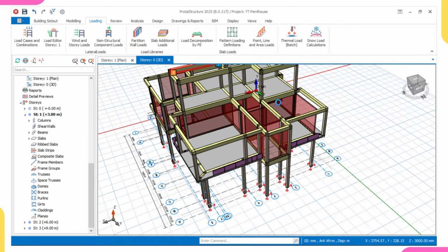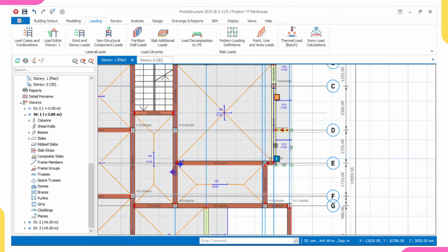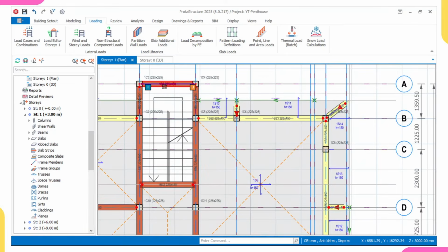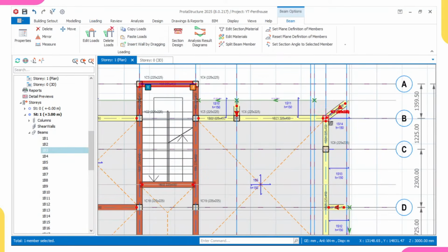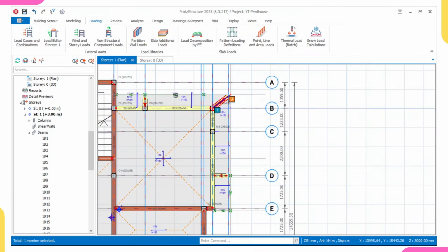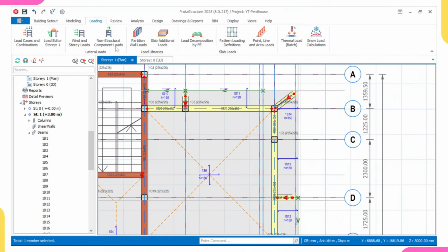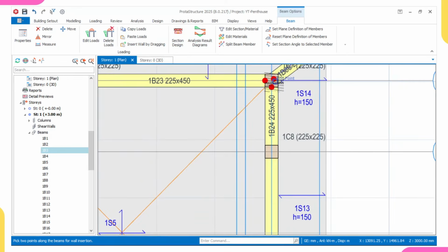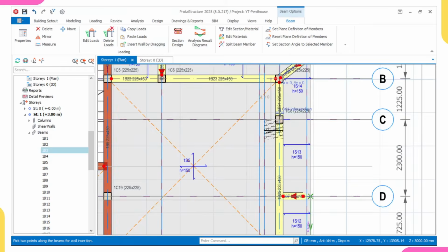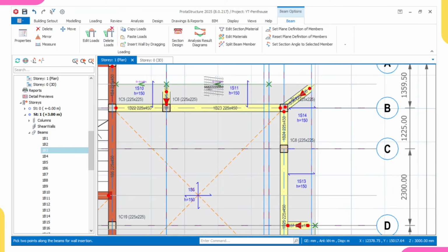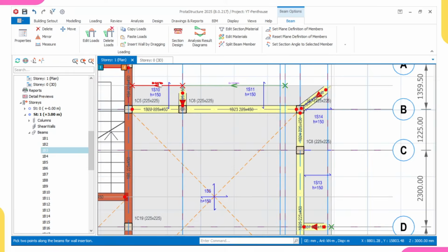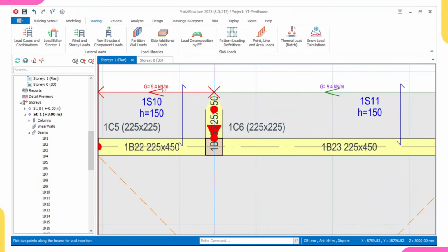So I'll come over to this point. This is part of the reason why you should calm down and do your detailing. Okay, I'll just click on this. First of all, you click on one of these, then this option will appear: insert load by dragging. So I'll select this. I want to apply line load because it is running on slab.